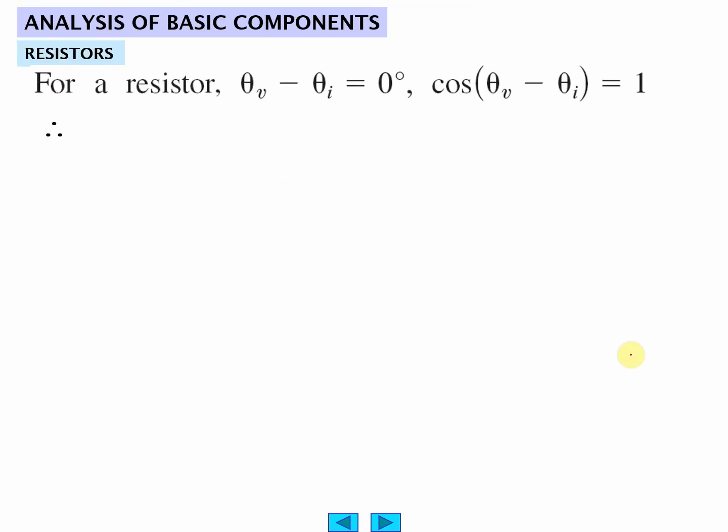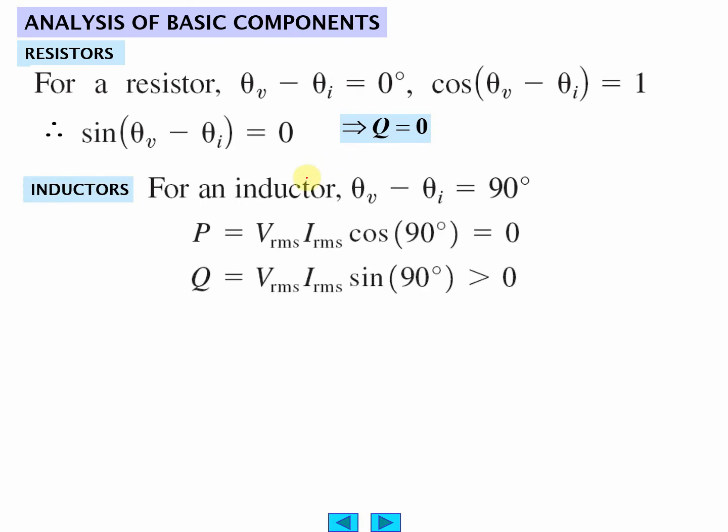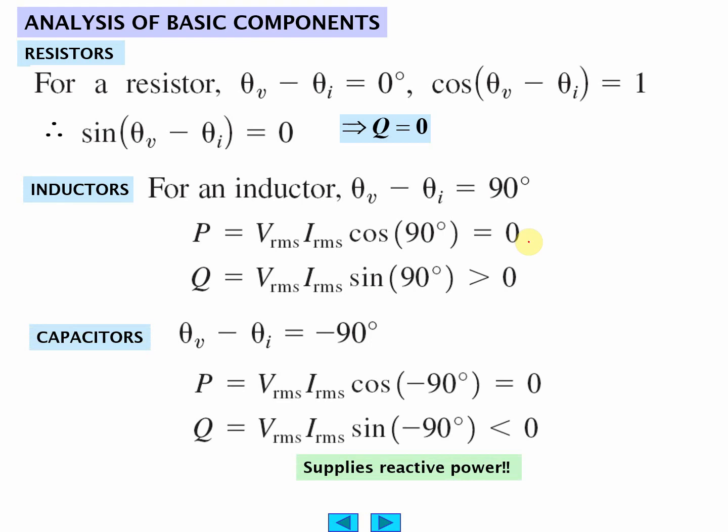Okay. So for resistor, its power factor is exactly equal to 1. So that's your I squared R. Inductor, you'll always have 0 for the real part if it's an inductor, and capacitor 0 for the real part. So inductors and capacitors, they're all reactive.